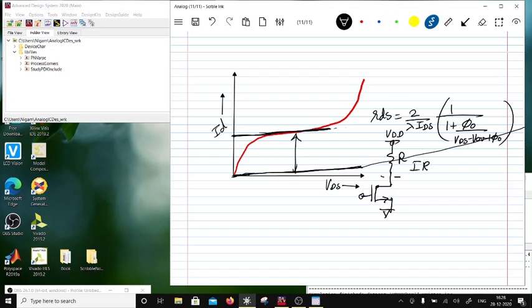In this case, we are not starting from origin. We are starting with a certain offset current and then building up this resistance. So these two resistances are the same, but in case of R, the net voltage across the resistor would be so large that it will swamp all VDD. While in case of MOSFET, we start with the offset, not with the origin. So then we are just dealing with this slope here. So the resistance here would be higher.